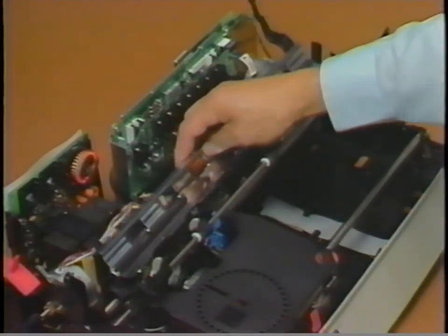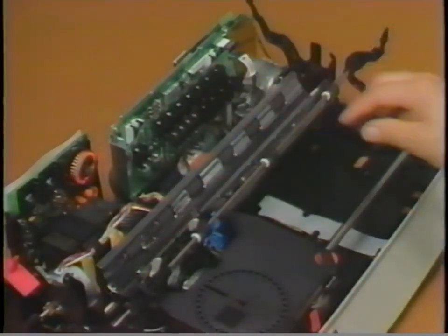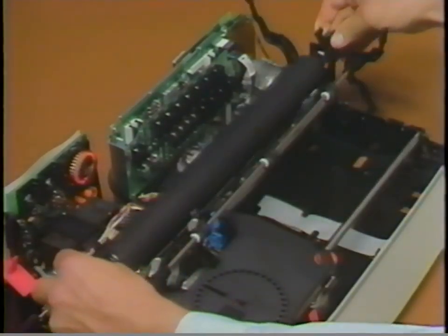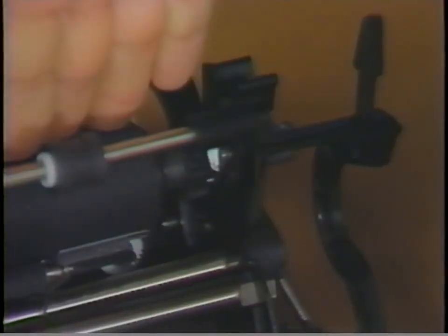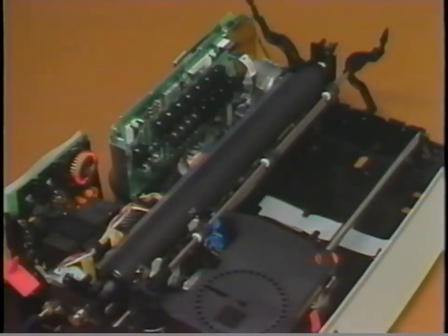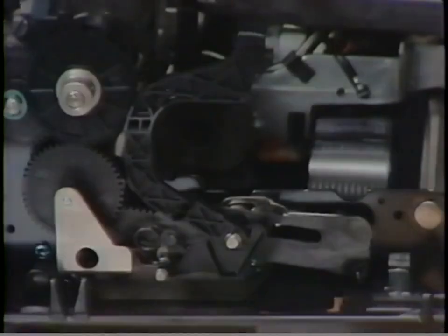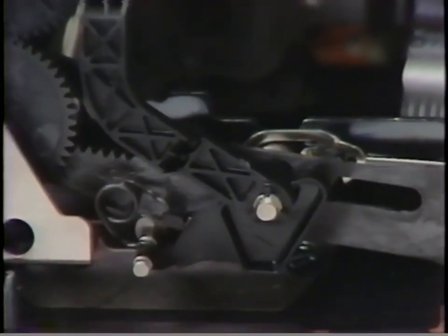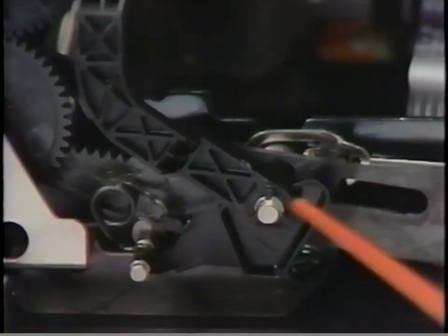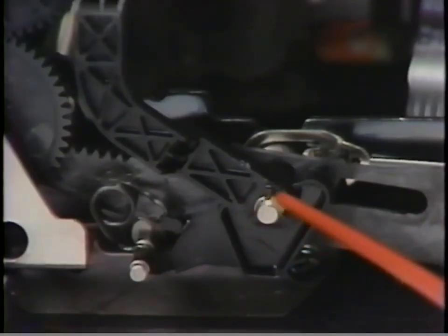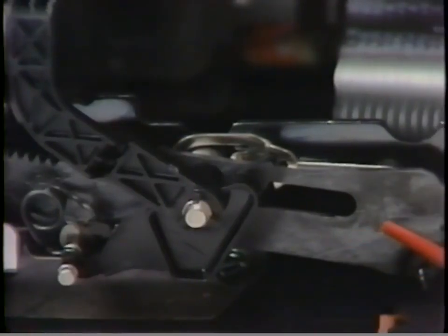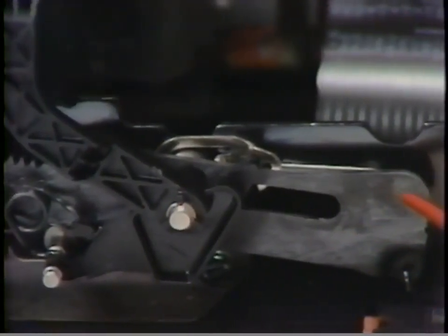Before installing the platen, be sure that the deflector is properly seated. Set the platen in the machine with the paper handler drive gear to the right. Push down on both ends of the platen to snap the platen latches into place. The paper bail arms are held in place by these tabs. The first writing line knockoff is mounted behind the left paper bail arm.